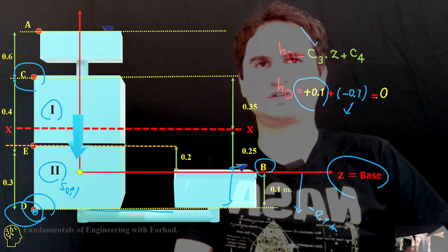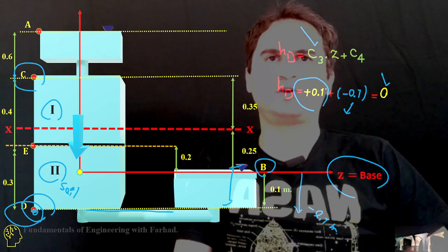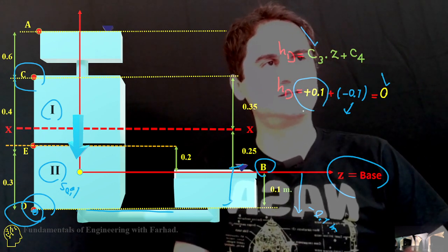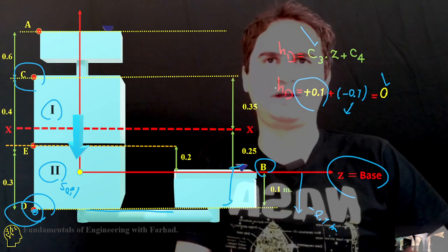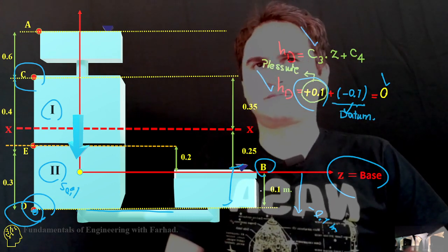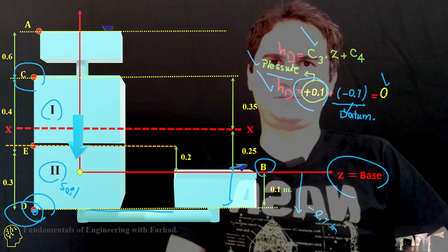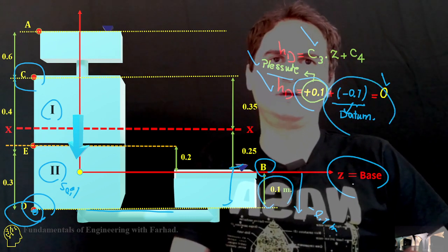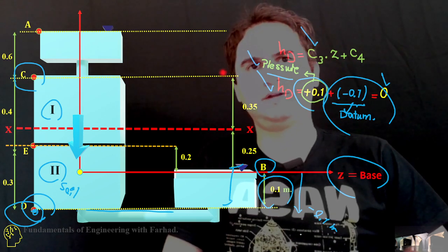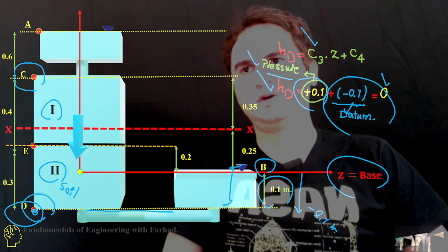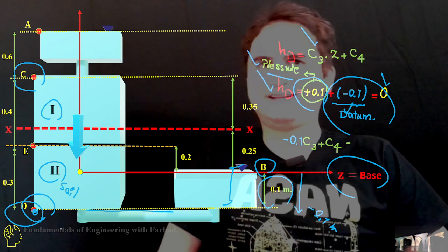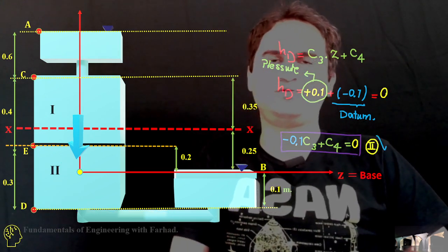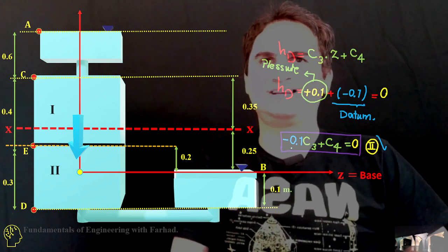It just gives us a total of zero for total water head for H at D. And again, this part is from the pressure of water. The positive part and negative part just comes from the measurement from our datum, which is climbing down to D. So in that case, if you jot down the second equation, it just gives you